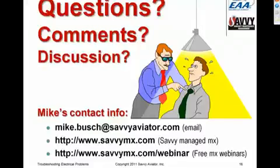All right. What's your opinion of using smart chargers while the airplane is on the ground? Using a smart charger is a good idea. It's a very good idea if the airplane is based in a hot climate, Phoenix or something, because the self-discharge rate of batteries rises extremely rapidly with temperature. It's less important for airplanes that are based in cooler climates.